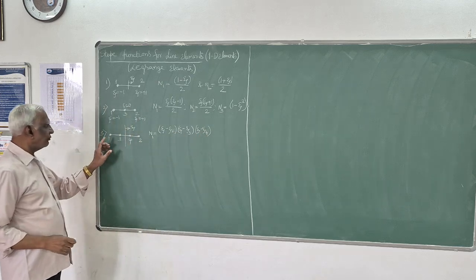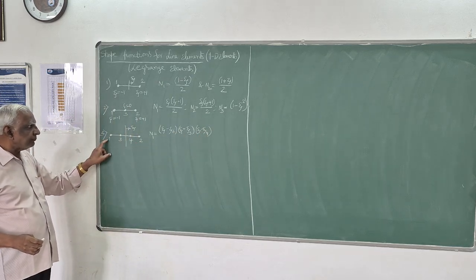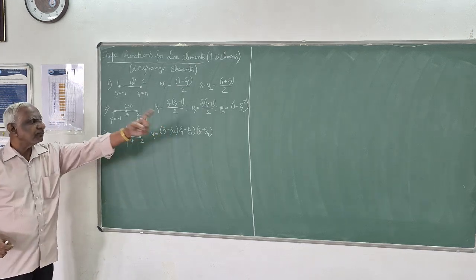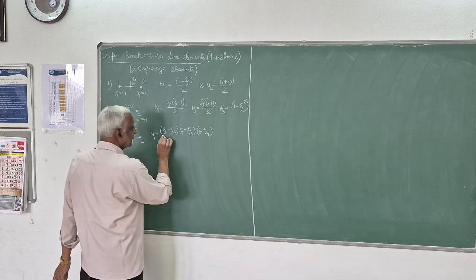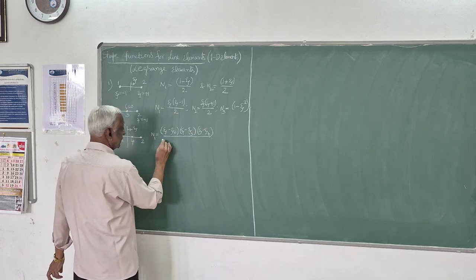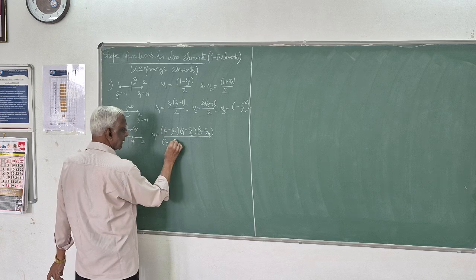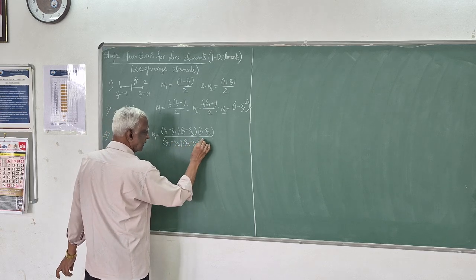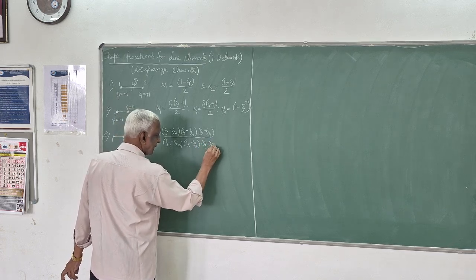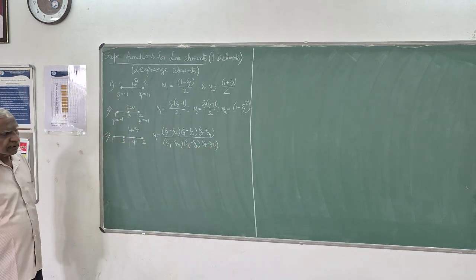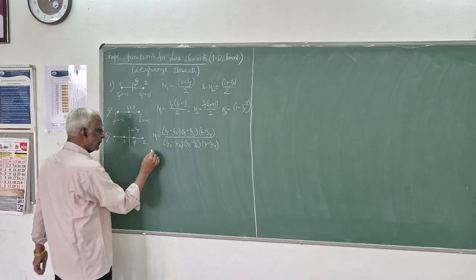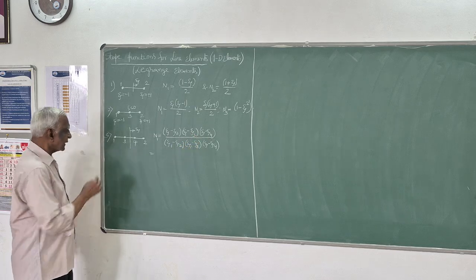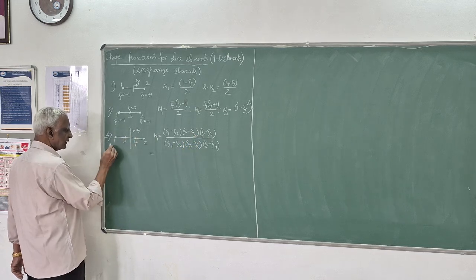The coordinates of all other nodes except node 1 we have to substitute and form the numerator, then denominator is psi 1 minus psi 2, psi 1 minus psi 3, psi 1 minus psi 4. This is the Lagrange formula. So substituting the values of psi 2, psi 3, psi 4, we will get the shape function.